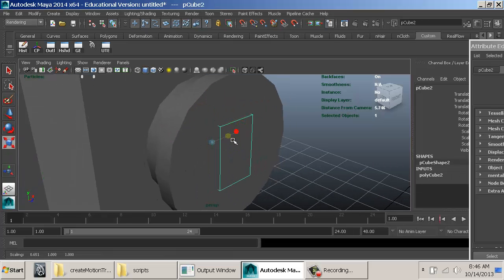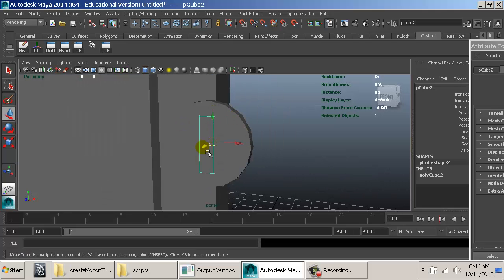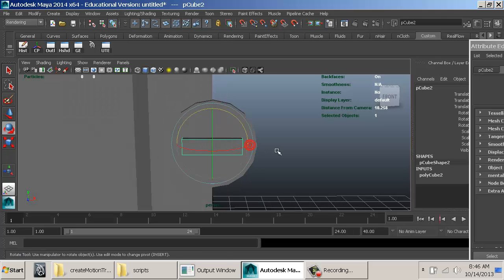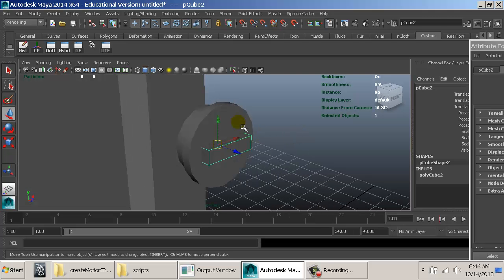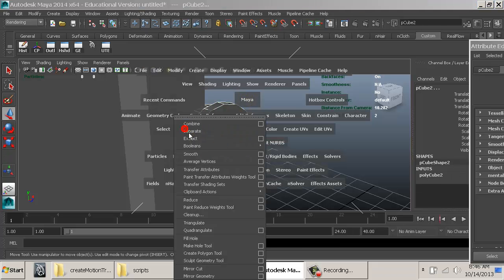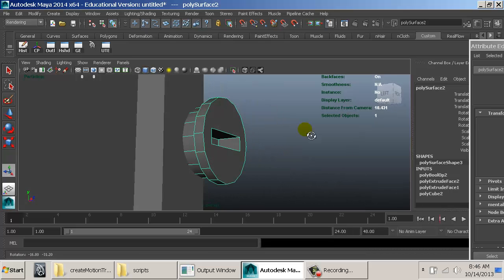So then I can scale it down, and the unlock position is vertical, like this. The lock position is going to be flat. So I'm doing this in the lock position. I'm going to click this because I want to keep it, shift click that, and say mesh booleans difference. And you can see how we have a nice little cutout right there.